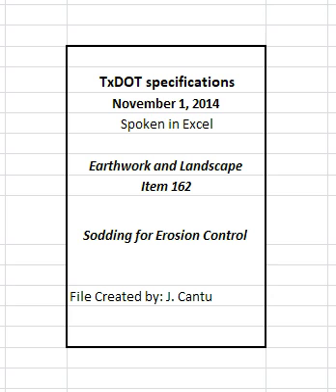2.3 Fertilizer. Furnish fertilizer in accordance with Article 166.2, Materials. 2.4 Water. Furnish water in accordance with Article 168.2, Materials. 2.5 Mulch. Use straw mulch consisting of oat, wheat, or rice straw or hay mulch of either Bermuda grass or prairie grasses. Use straw or hay mulch free of Johnson grass and other noxious and foreign materials. Keep the mulch dry and do not use molded or rotted material.